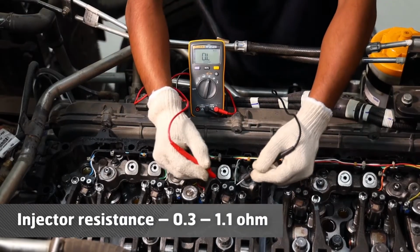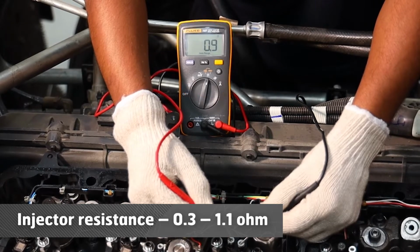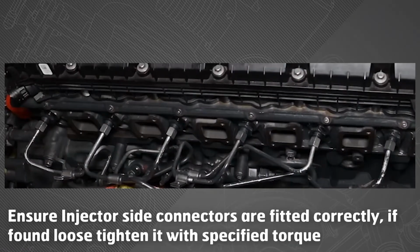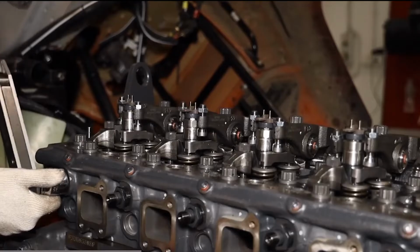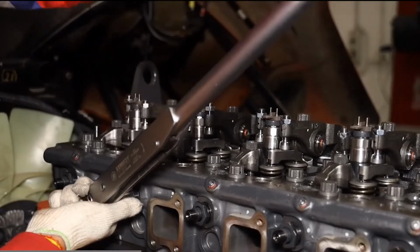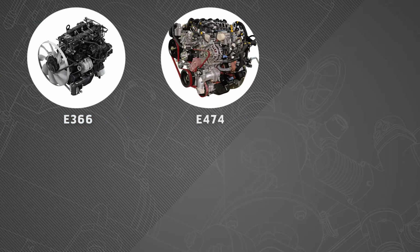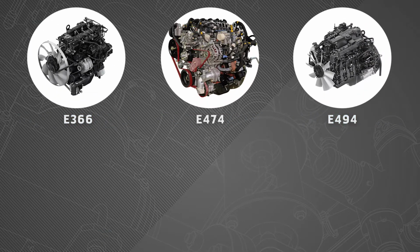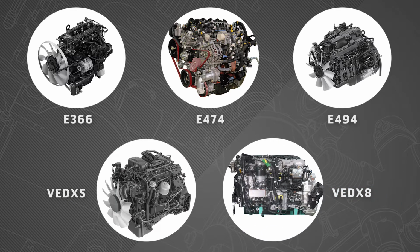Check the injector resistance 0.3 to 1.1 ohm. Ensure injector side connectors are fitted correctly. If found loose, tighten it with specified torque and sequence to avoid excessive back leak. Perform injector shutoff test for E366, E474, E494, VEDX5 and VEDX8 engines using DA light tool.